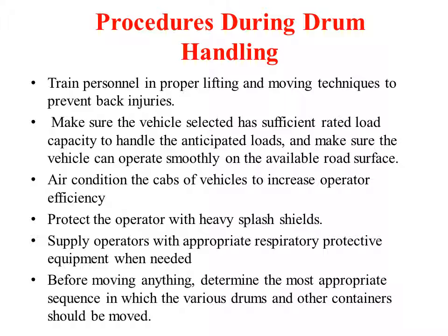Handle and dispose of corrosive waste safely. Once a container that had corrosive in it becomes empty, those drums or containers should be disposed of carefully and safely. Every manufacturer provides instructions on how all chemicals have to be disposed of.